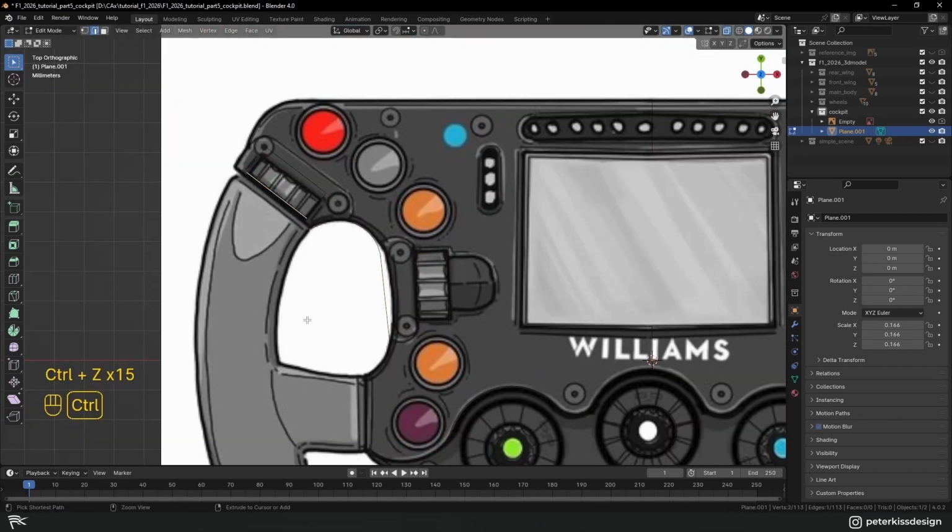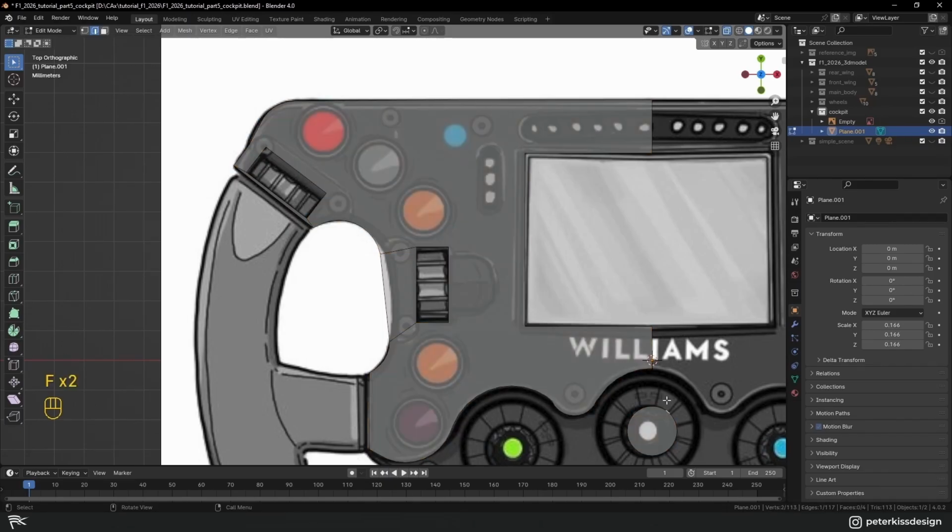So what is the easiest way to fill this now? We need to tell Blender that we don't want to fill the small rectangles, but instead keep them as a whole. We will do that by connecting one of the edges of these rectangles to the outer line. Now select everything by pressing A and exclude these 4 edges you just used. Now we have only the outline we want to fill, and we do that by pressing F. Just like that we have the main plane.